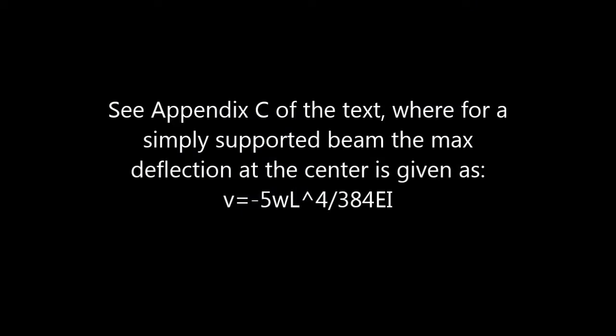So this is page 6. We just have a simply supported beam with constant distributed load, so our maximum deflection is going to be right there. We've used that, minus WL to the 4th over 384 EI. We didn't have that negative sign because I take positive down, so let me put that up here with this beam.